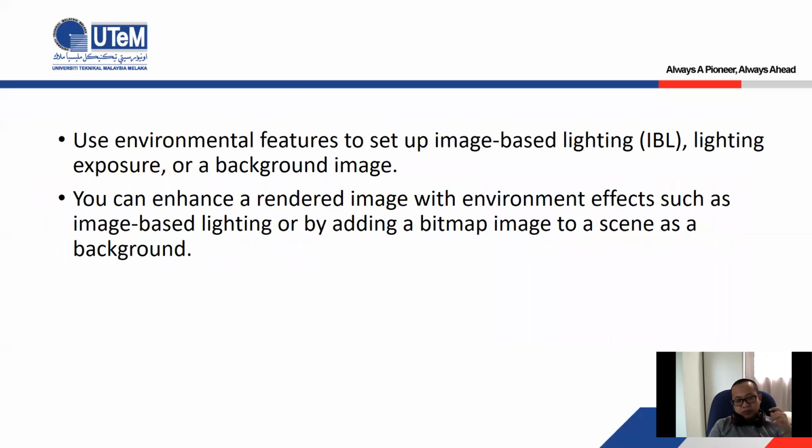Use the environmental feature to set up image-based lighting, IBL, lighting exposure and background image. You can enhance the rendering image with environmental effects, such as image-based lighting, by adding a bitmap image to scans as a background. Okay, later I will show you.